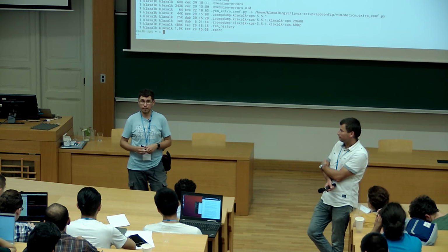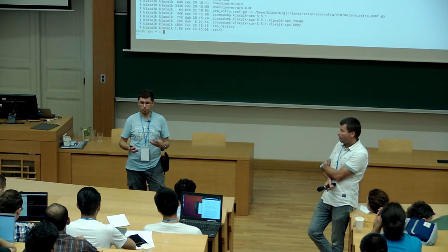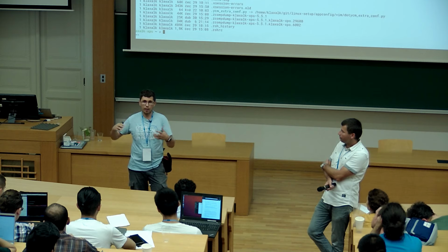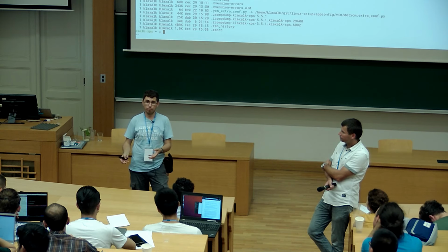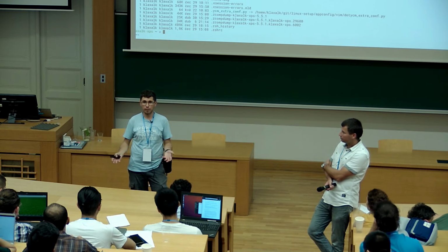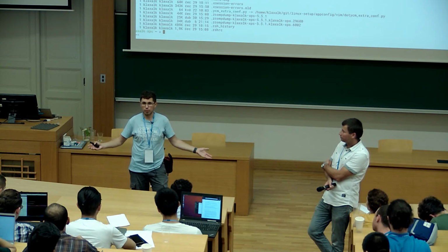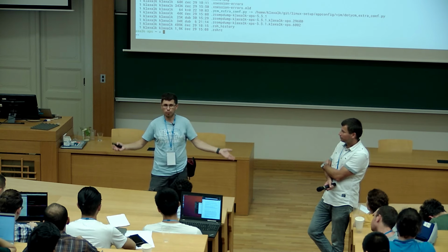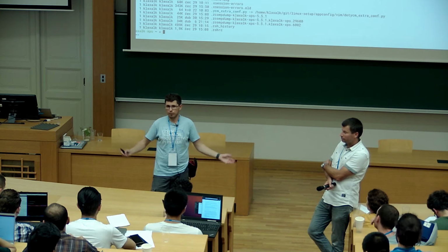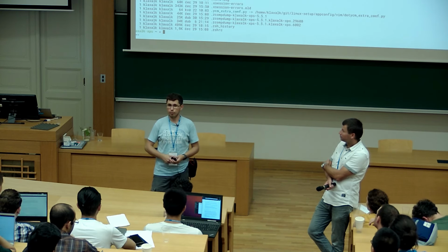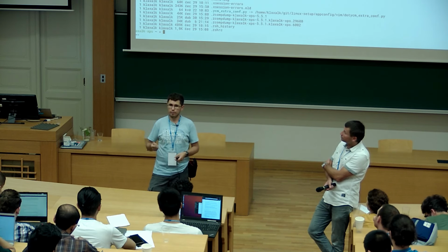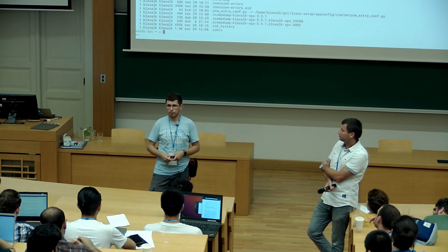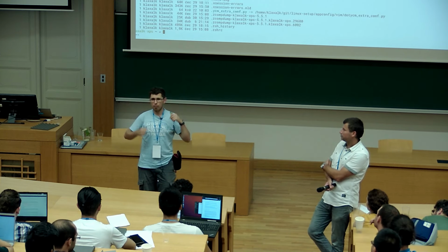For example, they don't let you arm the drone if the Pixhawk thinks that something is wrong with a magnetometer, but we don't use a magnetometer primarily, so who cares? You want to fly, but the Pixhawk says, I will not arm. And even if you set all the knobs in Pixhawk right, there are situations where we just pull our hair out and say, why?